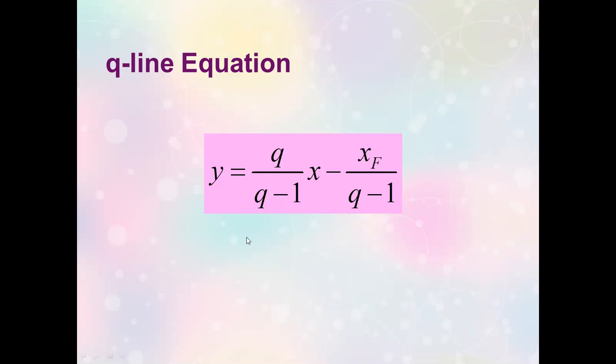determined. If you're going to ask me what's the heart of correctly solving a distillation problem, I'm telling you it's the Q. Because if the Q is wrong, everything that you will be determining is wrong. Of course, it is a given that you know how to represent the diagram. The diagram already clearly illustrates that you have a clear understanding of what the problem talks about and what it is requiring.